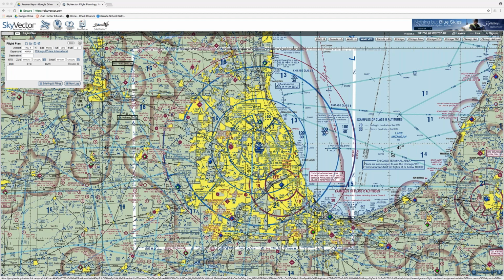These are altitudes. So what this is saying is that the top of the Class B airspace is 10,000 feet, and the bottom of this shelf here, all the way around, is 3,600 feet. Okay. So if I'm under one of those shelves, I'm not in Class B airspace. Say I'm flying at 3,000 feet in this area. I'm not in that Class B airspace. I'm under it, but I'm still speed restricted due to the safety and flow of traffic in the area. Okay. And like it says right here, 4,000 feet to 10,000 feet is your Class B airspace.